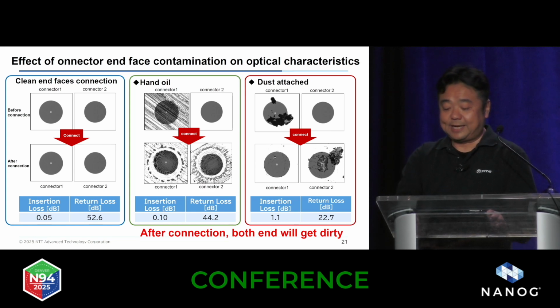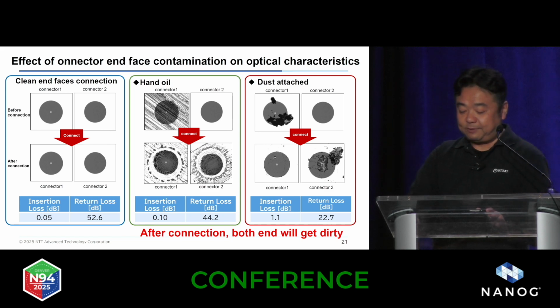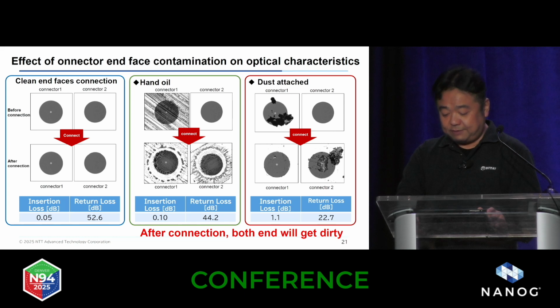We are often asked how much impact dirt actually has. So I will explain the result of the test to see what happened when there is dirt on the end face. On the left side is the reference value for when clean end faces are connected. The middle shows the data when hand oil was applied. Hand oil was applied to the optical connector end face by touching it with a finger, just slightly.